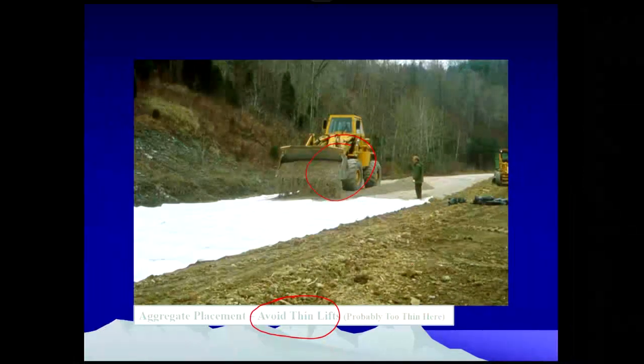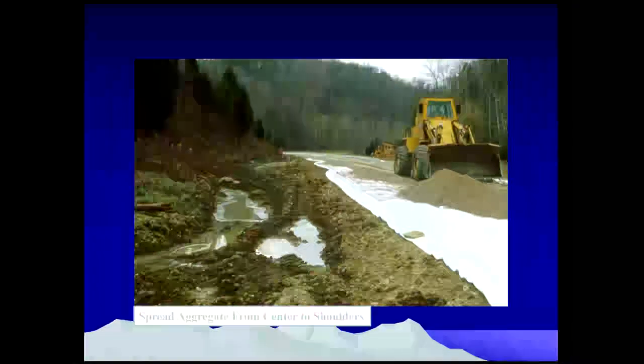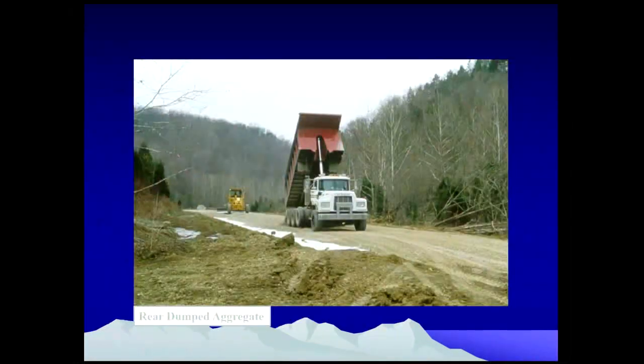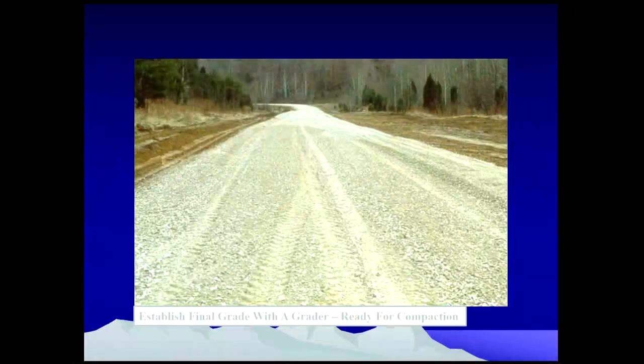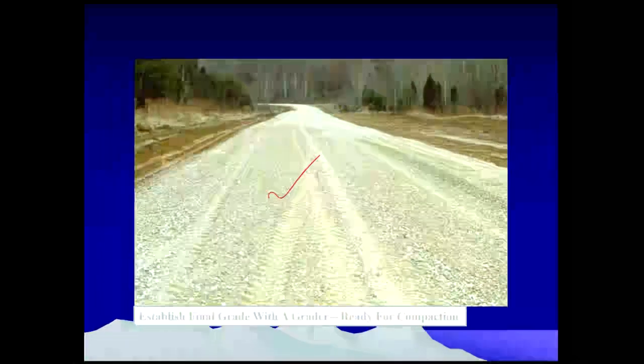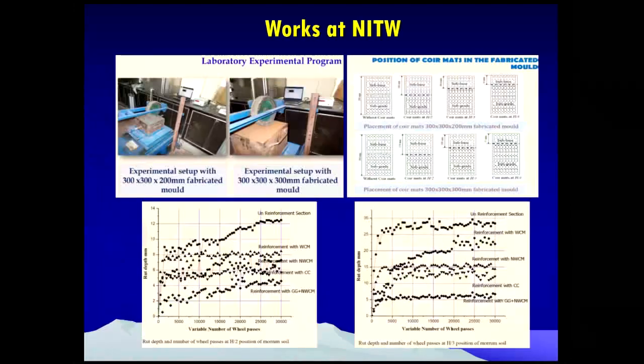It should not be 5 mm, 10 mm, or such things. You should avoid thin lifts. Spread the aggregate from the center to the shoulder part, dumping the aggregates and spreading them with a motor grader. Now you finally establish the final grade with a grader, ready for compaction. This is the sequence of activities that we do.